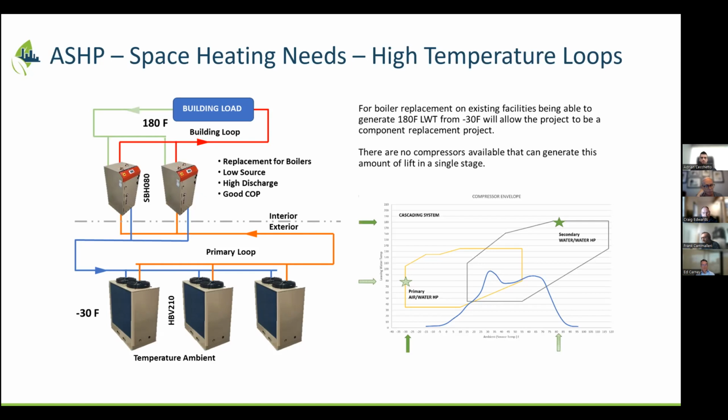So that's good. I'm not sure, Ed, if you had any comments you wanted to highlight or add to what I was saying. Well, just quickly on that, your two types of heat pump there. This topic is on air source heat pumps, the bottom 3 units, which sit outside and obviously take heat from the outdoor ambient. But in this application, they can only get to a certain temperature. That's why you would put in water to water units in series with these, and they can now take it up to a much higher temperature.